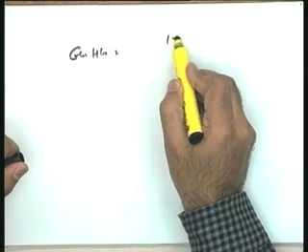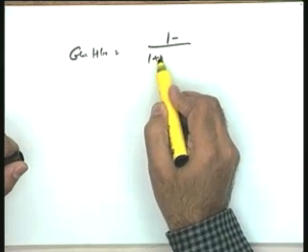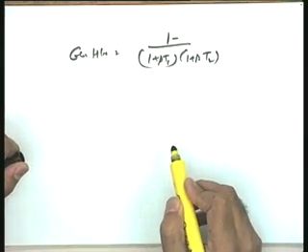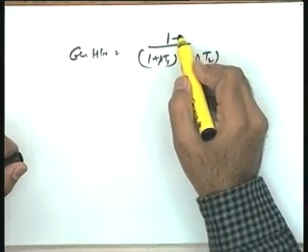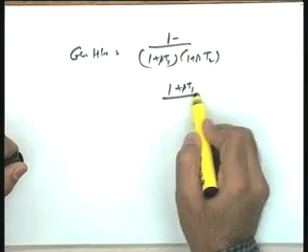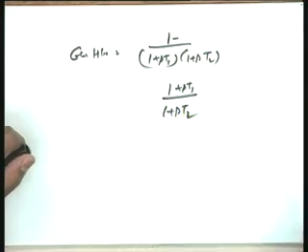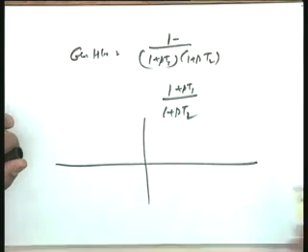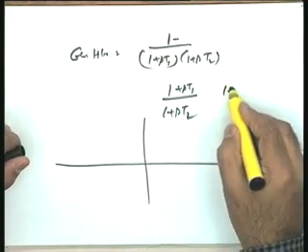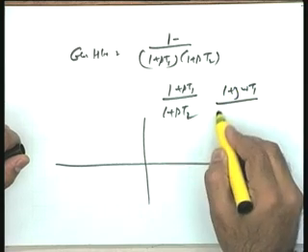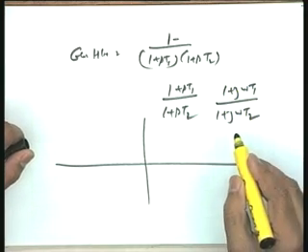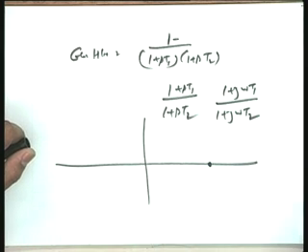So let me take G(s) = (1 + sT1) over (1 + sT2). Talking about the case when numerator and denominator degrees are equal. Come on, let us quickly get the rough plot of this. (1 + jωT1) over (1 + jωT2). Help me please, what is the value at omega equal to 0? This is your starting point.